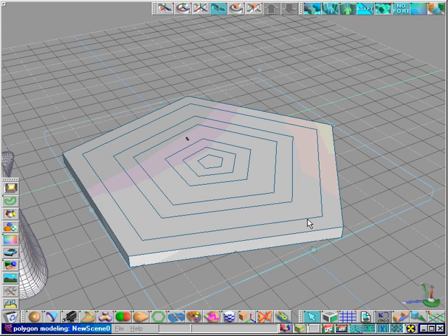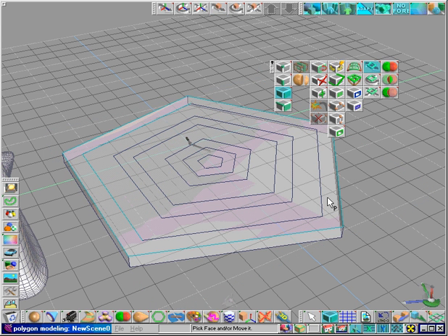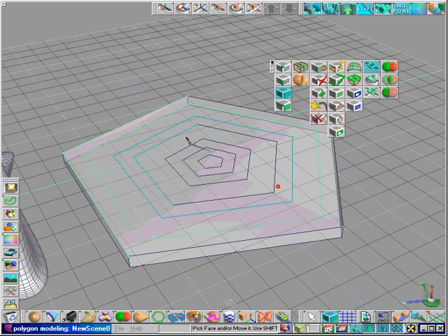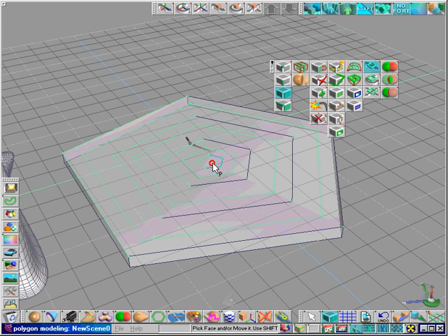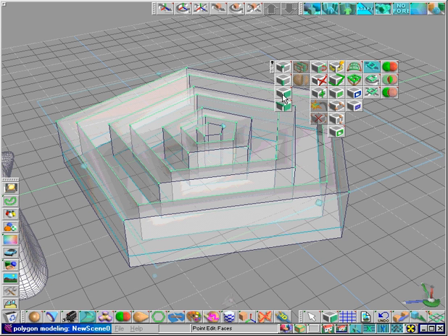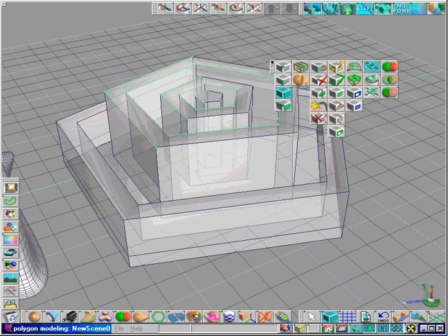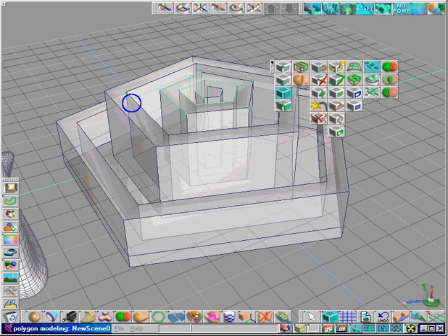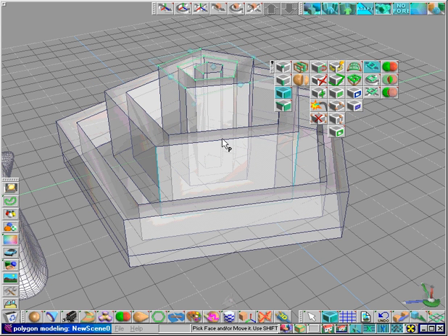Dividing up the face with the Polygon Bevel tool allows us to select the spaces between the lines as independent faces. These can be painted or manipulated as desired. We will select every other one and sweep them up once, adjusting the Z height a bit with a right-click drag. Deselect the outer ring face with a shift-click and adjust in Z again. With only the inner two faces selected, we will adjust in Z a little more. Finally, we will adjust just the middle face in Z.